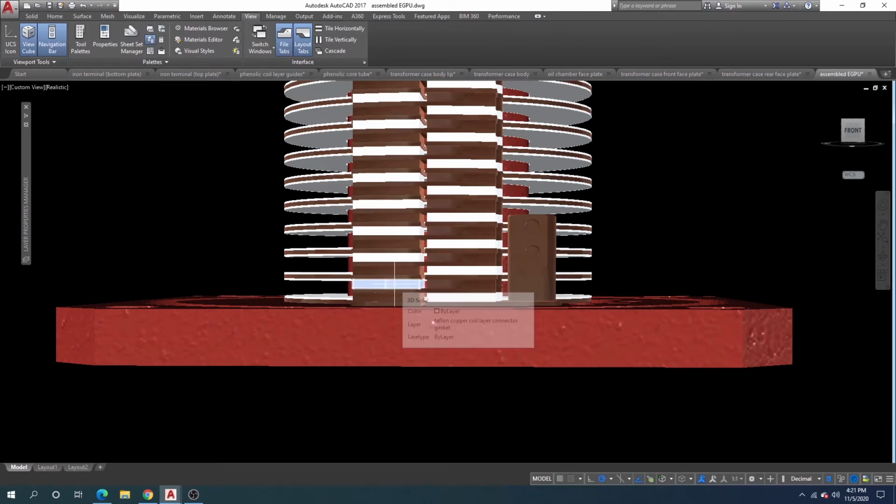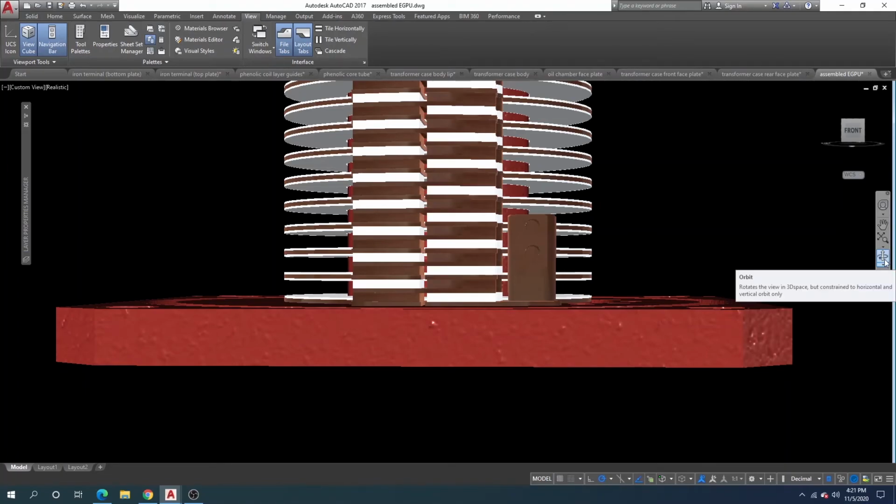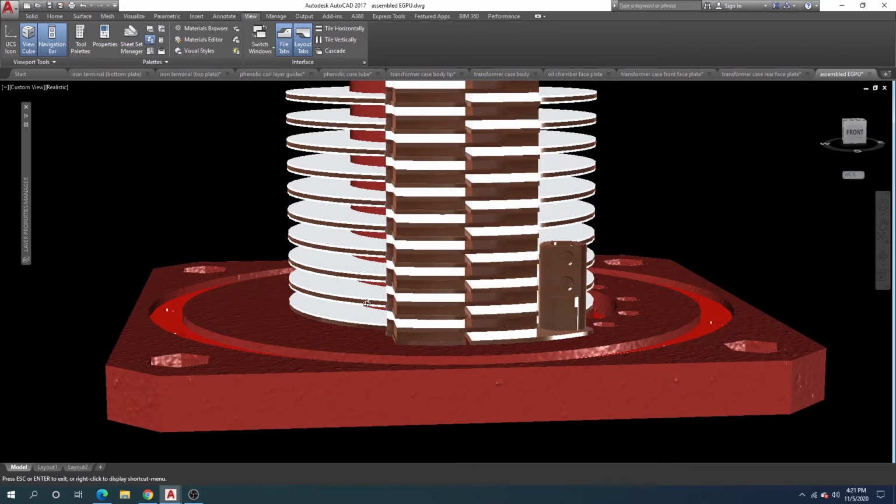This right here, these are called the Teflon layer, the copper coil Teflon layer to layer gaskets. They serve two purposes: electrical insulation and they're spacers. So when you stack this thing up, it will look like this. It will form this configuration, and you will have an actual coil like you see here. Okay. All right.